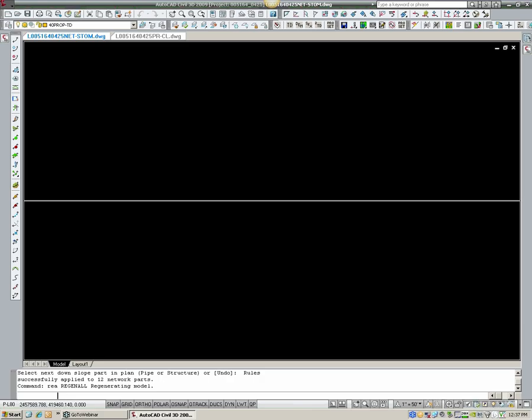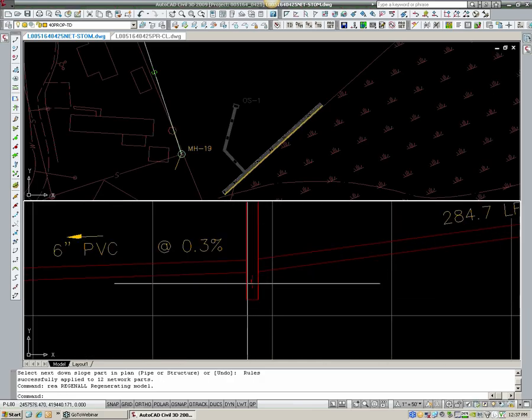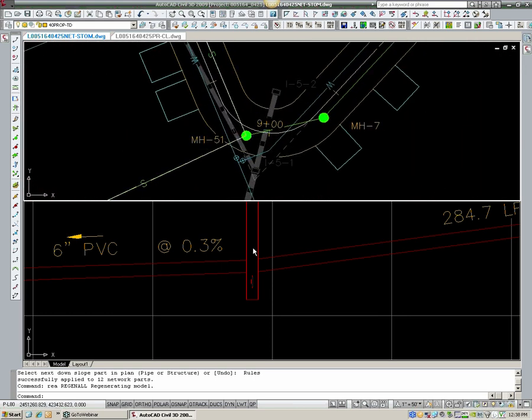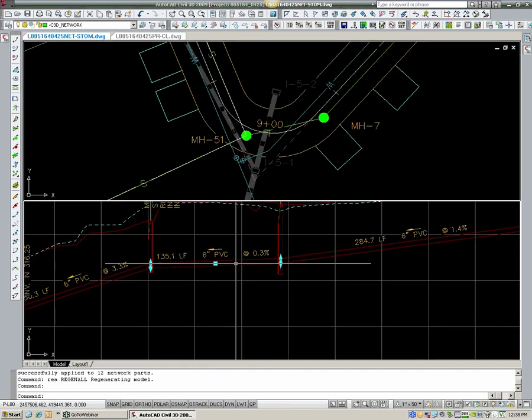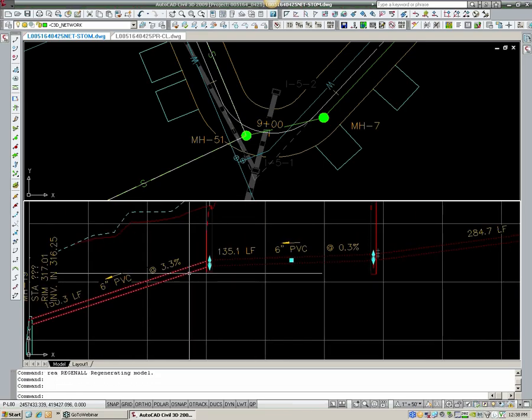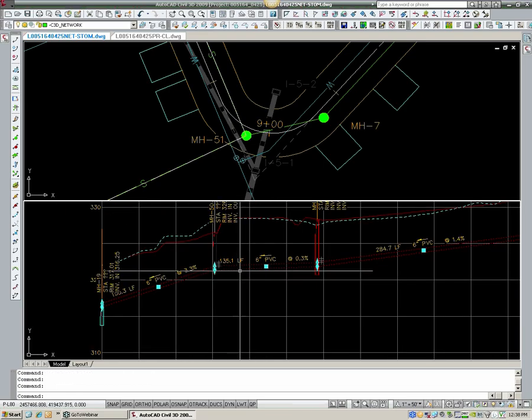The reason this structure is down a little bit farther here, it looks like there's a drop. Well, the reason being, and where I'd have to edit my design here, of course, is that this manhole line or this sewer line coming in is a little lower here, so actually this line can't be that high. To adjust that, I can simply trigger on a couple of the pipes here. If I want to trigger this or select the incoming pipe,